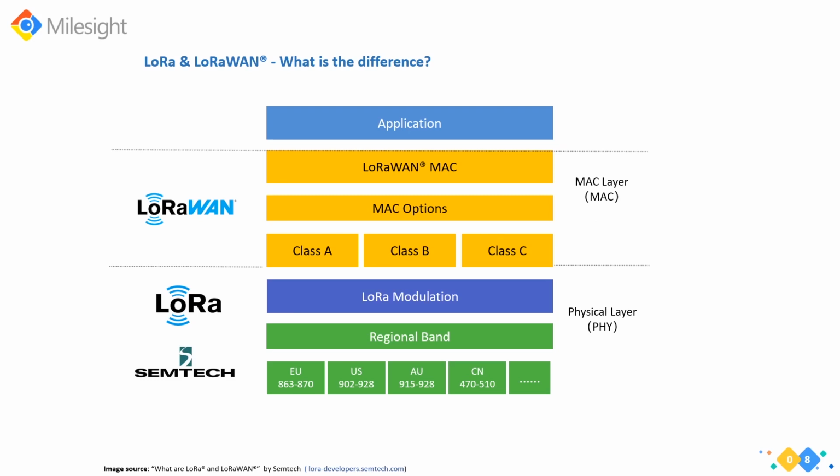You can activate devices on a network, you can count acknowledgement messages, and you can synchronize the windows in which your application can send data or send a command back to the end devices. So LoRaWAN looks like a bridge that helps you send commands and messages back to the end devices, to realize bidirectional communication.